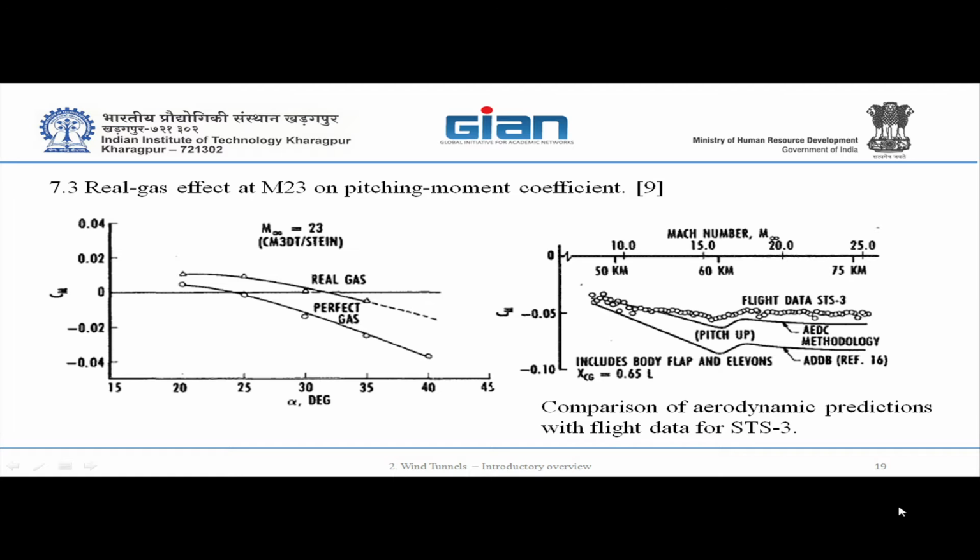It was not reacting according to expectation because of differences between real gas and perfect gas. The wind tunnels, usually the cold wind tunnels, work as perfect gas. And what I was discussing earlier, the interaction and the complicated regions, are different when you're talking about real gas. The bow shocks are sitting differently, so the moments are different. And it came out in practice.